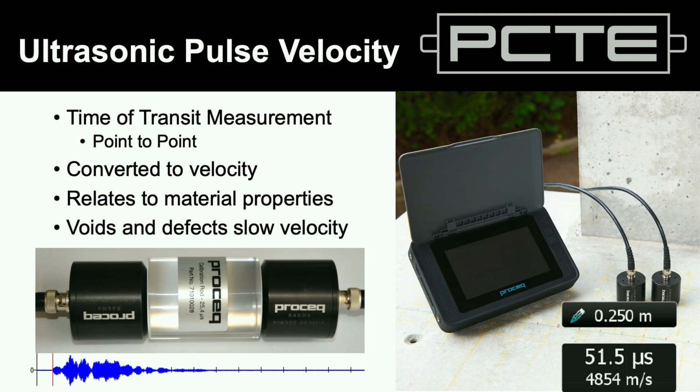Now, if you're a researcher, you can do all sorts of interesting signal processing outputs, get lots of sensors and do all sorts of clever things. But for people working on site, I encourage you to limit yourself to 2 points of interpretation, which is the time of transmission, so your velocity measurement direct, and maybe a little bit of amplitude analysis, which is how strong was the received signal. But please don't go thinking you can see shapes in the actual waveform receipt itself, unless you'd like to know who you're going to marry next week.